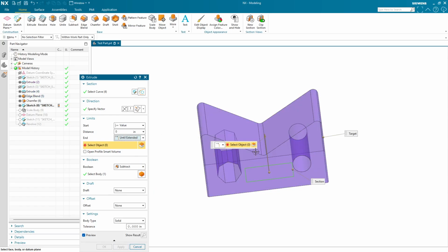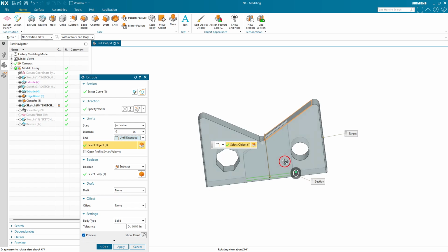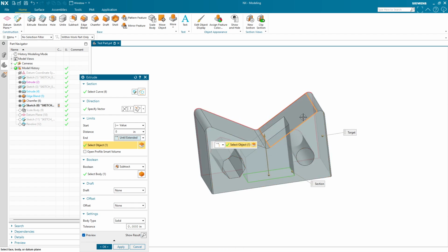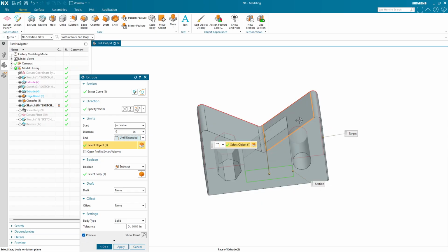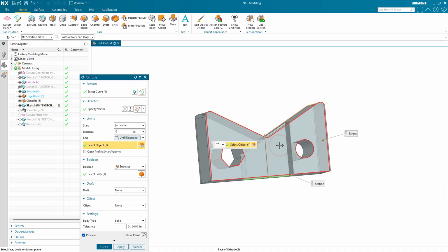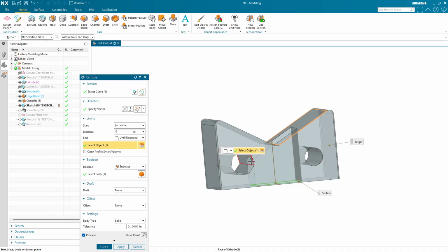So I can do until extended, extrude up to that, and it extends the thing I've selected, and it's basically going to chop this off at this angle because it's extending this plane I've selected. It's extruding until extended. So once it hits this virtual plane over here, it stops and it no longer continues up to the tippy top surface.